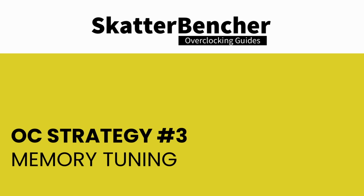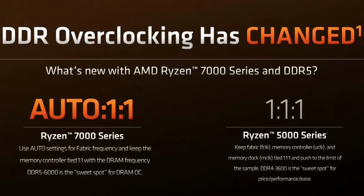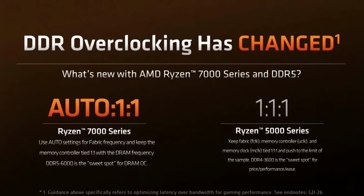In our third overclocking strategy, we try to tune the memory subsystem. Now, on AMD Granite Ridge Ryzen 9000 CPUs, the memory subsystem consists of three major parts: the Infinity Fabric, the memory controller, and the system memory. We also refer to these as the F clock, the U clock, and the M clock. First generation Ryzen overclockers know that these parts used to be tightly coupled together, but on modern Ryzen processors like the Ryzen 9 9950X3D, we can tune them independently.